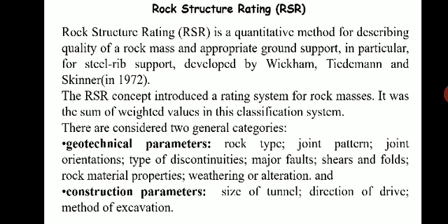So in RSR, that is rock structure rating, the nature and distribution of structures or structural features within the rock mass may have a dominant effect on the response of the rock mass to mining, okay, mining, tunneling. So the structure can influence the choice of mining method and the design of the mine layout.